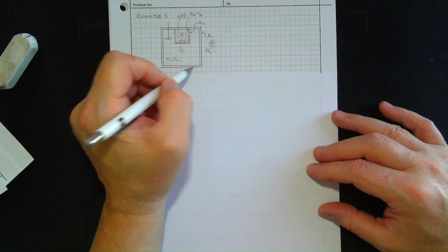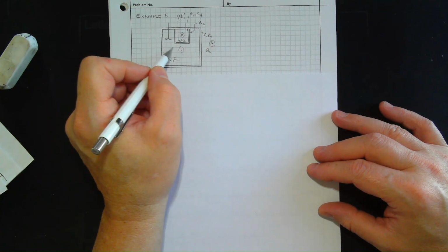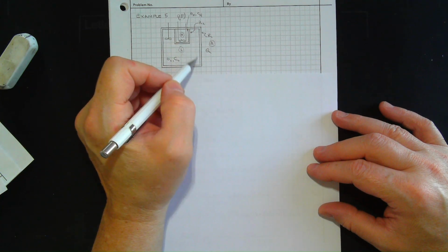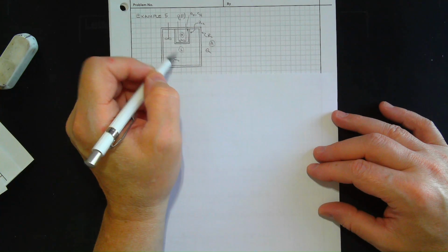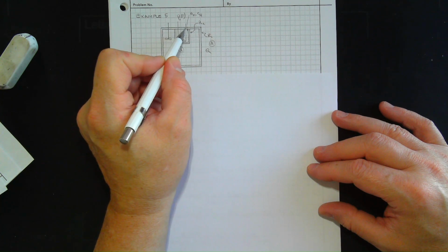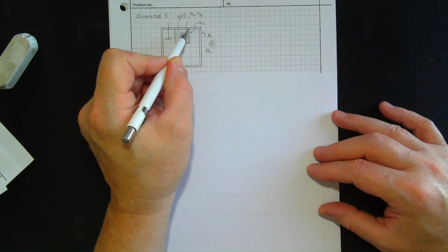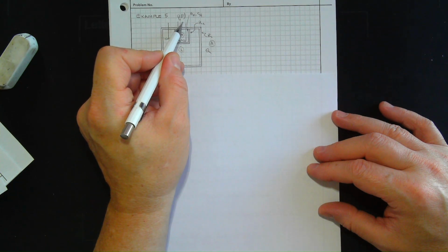And we have two resistances. There's R1 with respect to the outside. So assuming we're not looking to heat the outdoors, R1 is probably pretty significant. Okay, so we want to retain the heat in this area. And I'm going to assume that this section here above the hot zone is perfectly insulated. So there's no heat coming out this way.